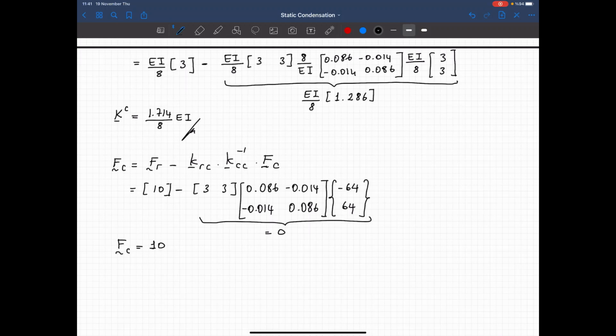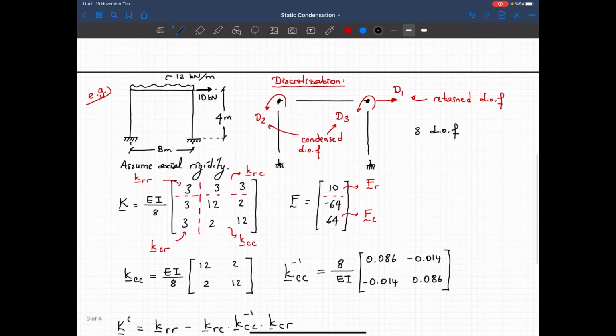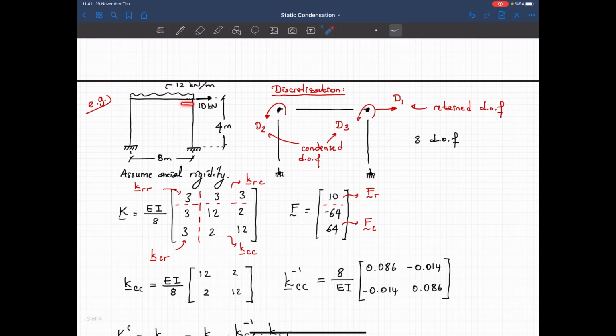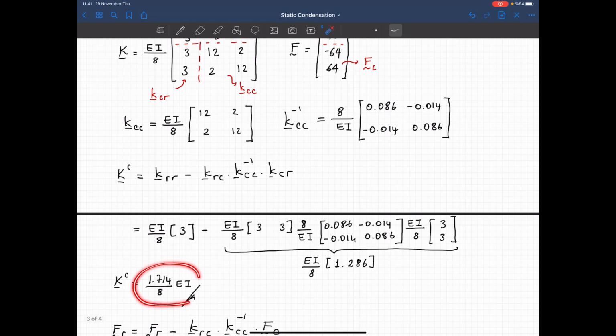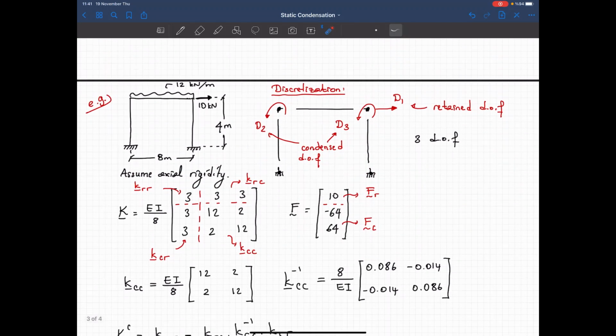So this is something that we expect, right? Let's repeat. We find out the stiffness coefficient in this direction. In other words, if I want to create a unit displacement in this direction, I have to apply this much of force. Now, but I have 12 kilonewton vertical force and 10 kilonewton lateral force applied to that structure. So I'm trying to figure out what is the equivalent lateral loads of these two that will move this structure in the lateral direction.